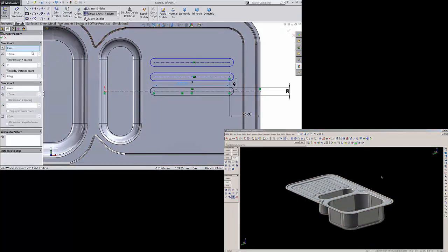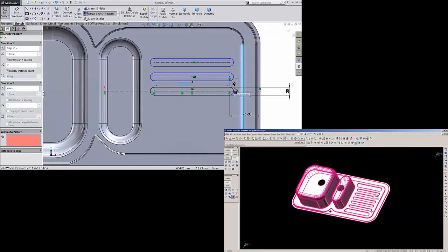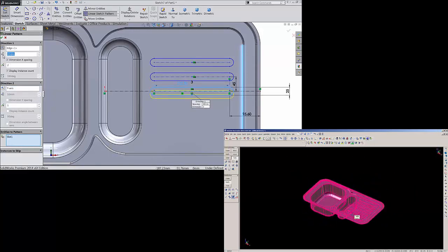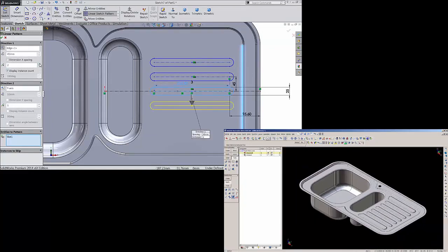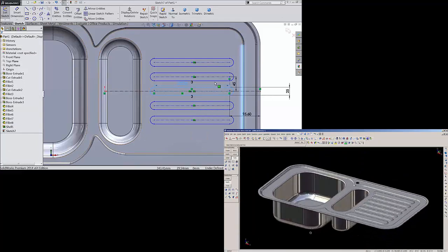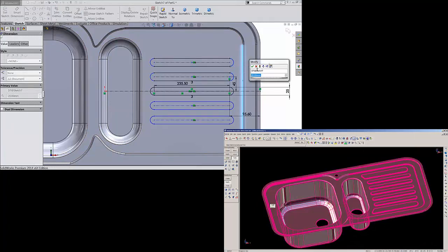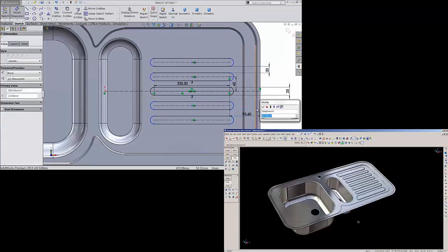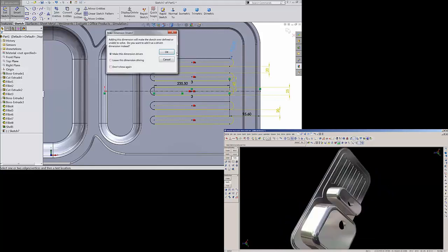Now again choose this line as an axis, and here select this, select reverse direction, keep 45 mm, select 3 numbers. Okay, now let's check the gap between these two. It must be 20 mm. You can see it here, 20 mm, and the corner 12.5 mm.